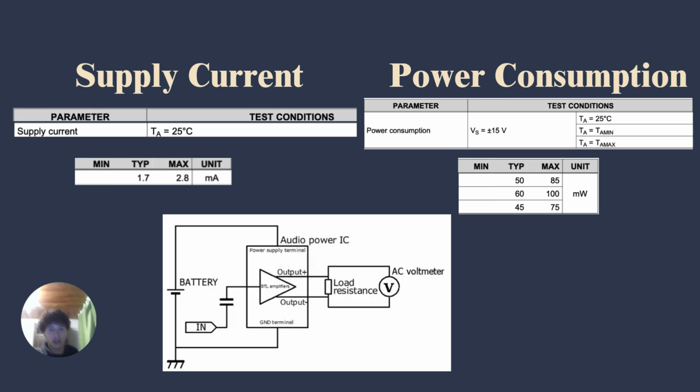In contrast, high performance op amps used in audio systems or instrumentation may consume hundreds of milliwatts or more. Excessive power consumption can cause heat buildup, reducing efficiency and reliability. To optimize power usage, it is important to select low power op amps, design efficient circuits, and use power saving techniques to extend battery life and enhance performance.